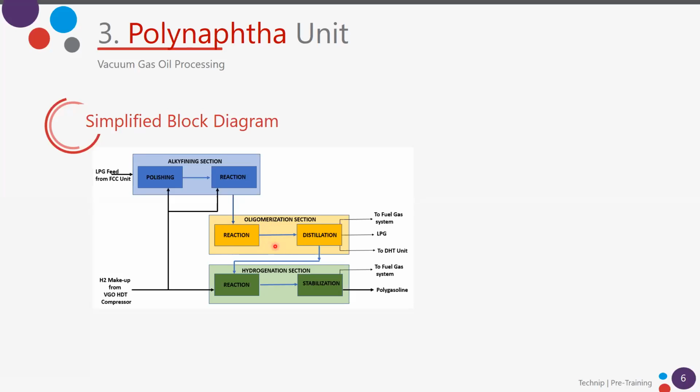So that's why they make all these olefins through this reaction, but then they have to hydrogenate part of them. You cannot compress all the sections into one section. So each section has its own objective. So that's why you go step by step doing your own conversion, and each catalyst will have its own selectivity and its own mechanism and what to target and what to convert. So you cannot merge the two sections together.